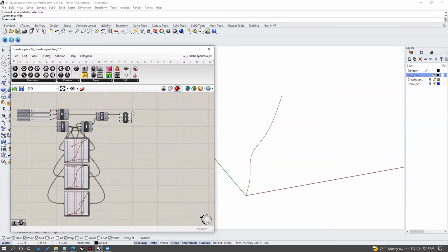This process is going to involve dividing this curve, extracting perpendicular frames along that curve, and then lofting between profile curves relative to those perpendicular frames, making that lofted geometry solid, and then making some transformation adjustments like we did with these graph mappers so that we have some control over the outcome geometry. So the first thing to do is to make a divide curve component.